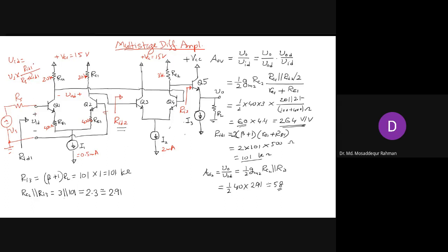So that's why we try to have as high as possible input resistance, so that will minimize the loss. In the ideal case, if RID is infinite, then VID will be exactly equal to VS. That's why we said that an ideal amplifier should have infinite input resistance. That is how we minimize the loss at the input side, by having very high input resistance.